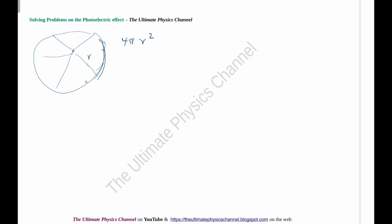And therefore, at that distance, what will be the flux? That area we have to first calculate. So that is 4 into 3.14, or we can even keep it as pi, times r, which is 2 meters as given. So 2 squared is 4, so it is 16 pi. That is the surface area of a sphere at that particular distance of 2 meters.